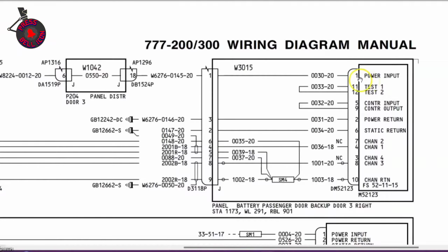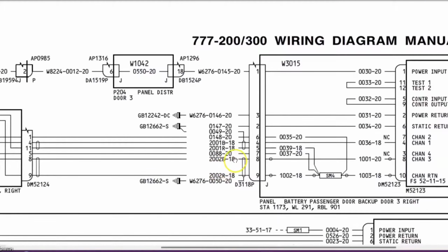The idea for selecting this diagram for this system is this. You can see over here there are different gauges of wire installed on one particular plug. The gauge is 20, here the gauge is 18, and also the contacts are different inside this plug. There are two types of contacts which have different engaging end sizes. So that's why I have taken this diagram and this system. You can also see there is one SM4 which is spliced inside the bundle over here, and there is also a different type of wire. This is multi-core wire, blue and red, which is shielded and it is separately grounded.